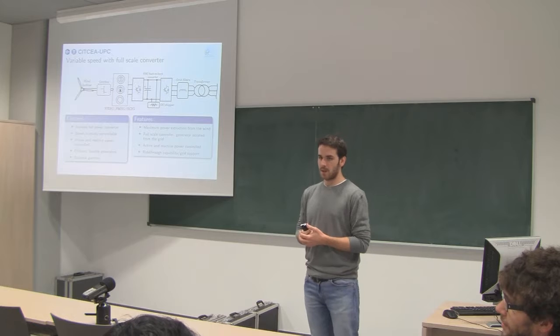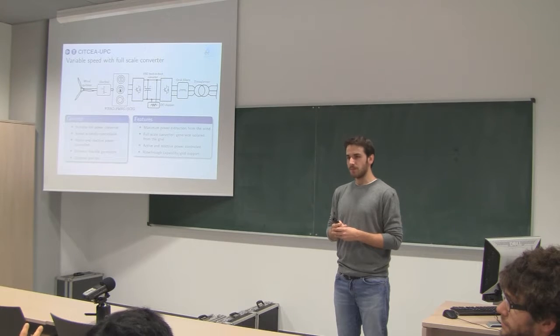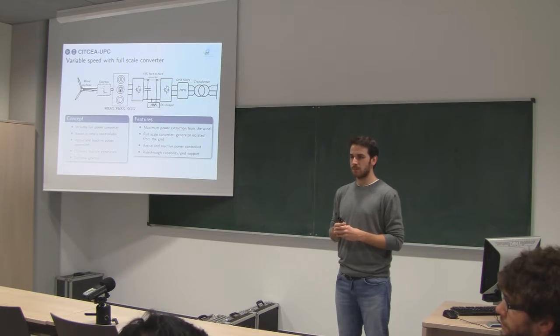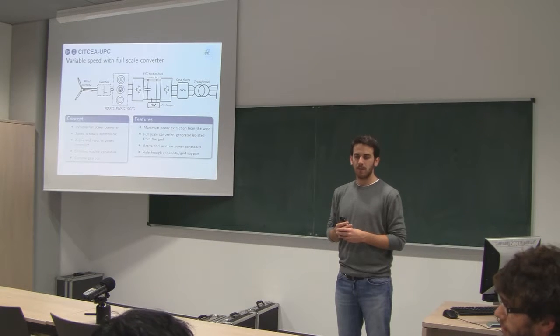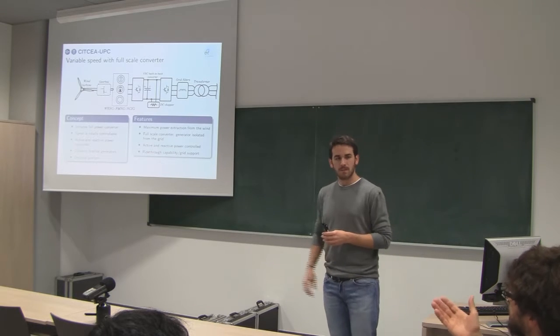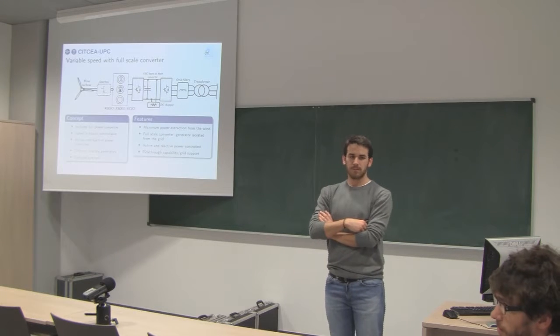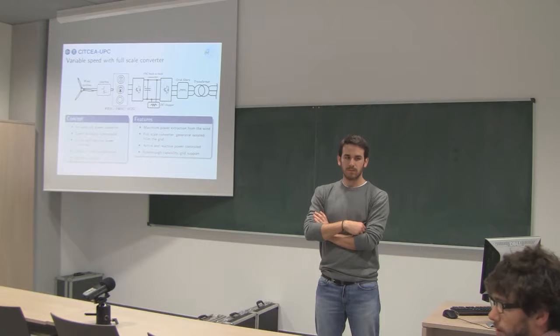Yeah, definitely, you have to. Otherwise, I thought it could be just a matter of induction machines, where you cannot vary the rotational speed very much, so you had to vary the rotational angle of the axis of the blades. But still, in all the configurations, the blades are moving, right? Yes. In the older versions it was not like this, but nowadays everybody does, because you rate your system for a certain amount of megawatts, and the structural system is also rated like this. So if there's a storm or a very high wind, you only get some power out of the wind.